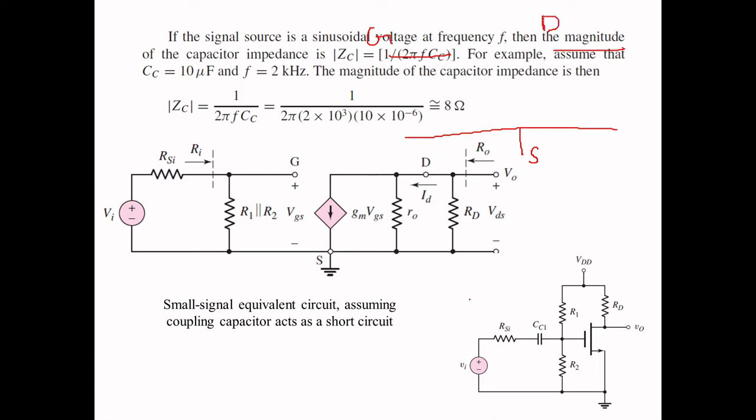So I will explain here. First we put a mathematical model for this MOSFET. What will you have? You have a VGS. Then you have a dependent current source, which I explained in the previous slide. Then they have considered R naught, that is the early effect resistance. So the mathematical modeling is over.